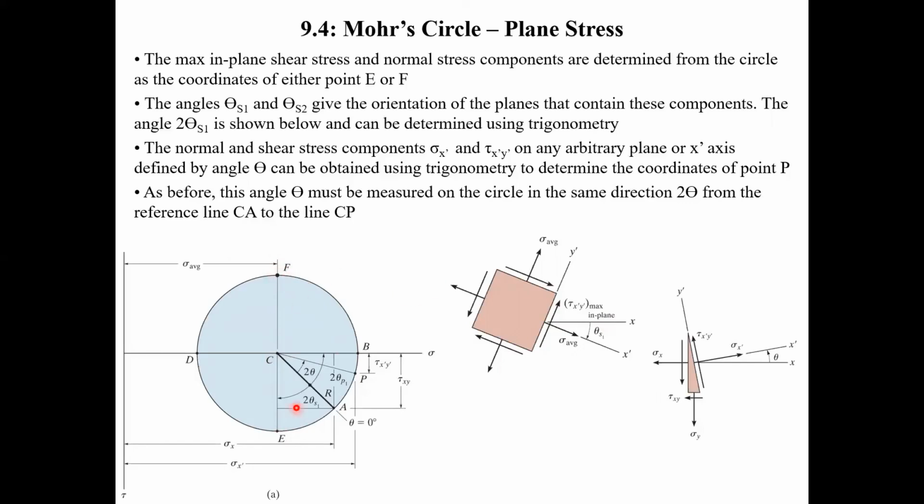So again, we don't really need to calculate it twice because it's going to be the same value. They're just going to be going in opposite directions according to our sign convention and according to our shear equilibrium on our element. If it's going up in the y direction here, it needs to be going in the positive x direction on this face here. And then make sure that the points meet at opposite corners so that you're in rotational equilibrium.